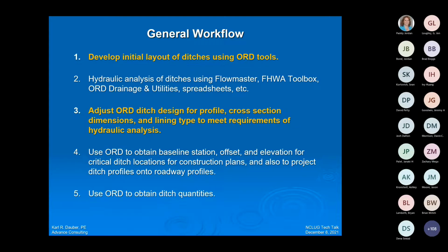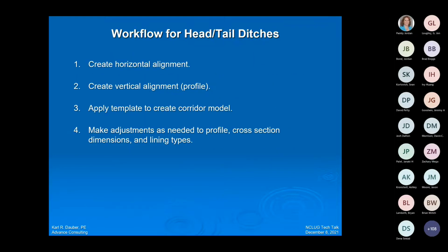Now today, I only have time to cover a few items. I'm going to cover items 1 and 3: using ORD to develop the initial ditch layouts and using ORD to adjust those ditch designs to meet the hydraulic requirements. I want to briefly review the workflows for head and tail ditches, as well as lateral ditches, and just note how they're a bit different.